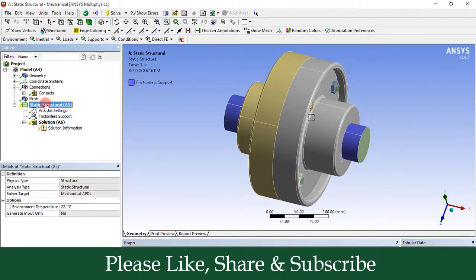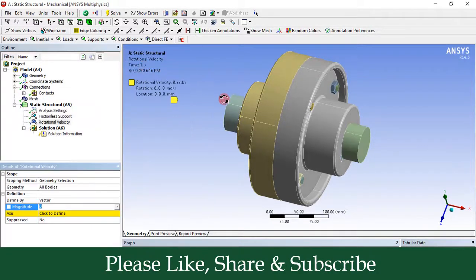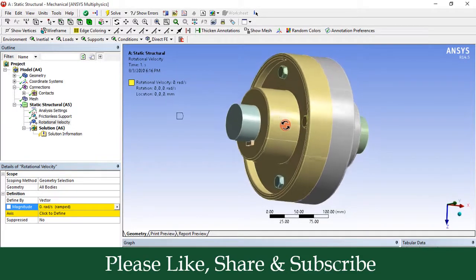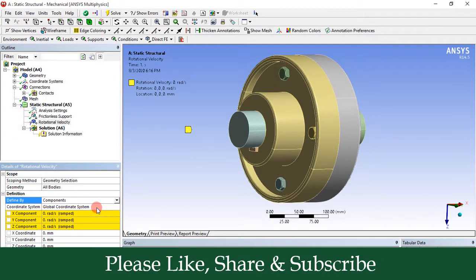Now right click on static structural again, go to the insert, go to the rotational velocity, and now we are going to apply the rotational velocity on the input shaft. But here we have to define this rotational velocity either by component or by vector. So I am going to choose this option components. So now I have selected the option components.